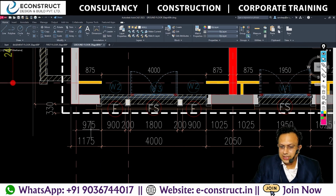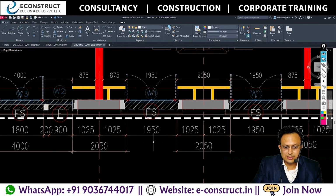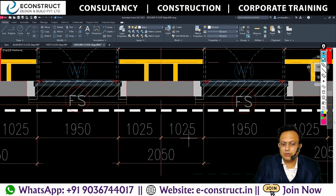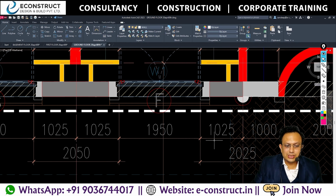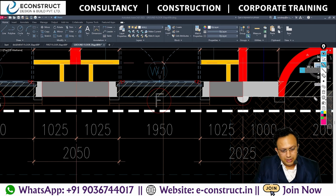The dimensioning was given in terms of mm, so you can see that over here. It is in mm distances. Actually, you will see meter and mm. Why is it in mm? Because the accuracy is quite more. But you will see that at no point is the dimension like 1012. The dimensions are given in multiples of 25, because 25 mm is 1 inch.